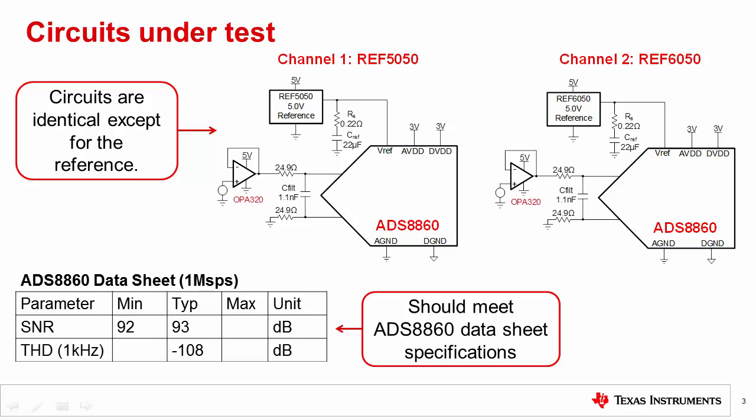The reference input of the ADC has significant fast-moving current requirements. In this experiment, we will see that the system using the wide bandwidth reference has better AC and DC performance because the reference can respond to the ADC's rapid transient current requirements.